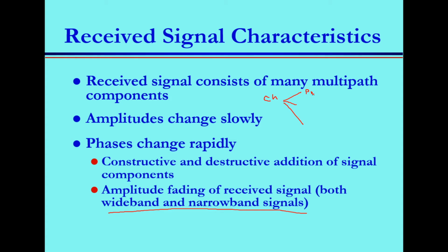What does this say? This says that the delay spread, Tn of t, this one, represents the last copy of your multipath that you receive at the receiver, and this is the first. So this is the first copy you receive from line of sight, and this is the last.